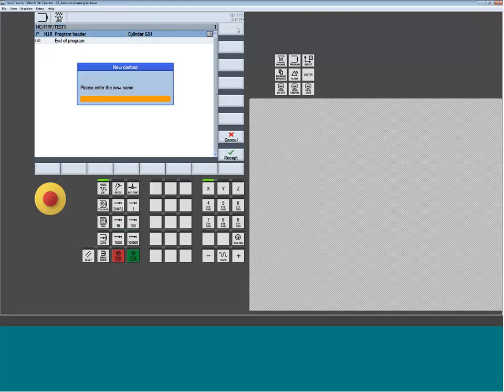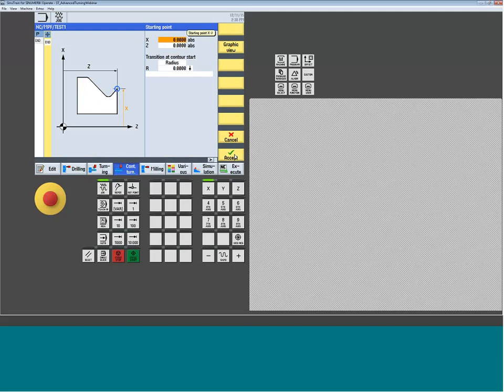Now we're going to want to go in and create a contour. The name of the contour, as in the past, doesn't really have any bearing more than it's just a reference for you. If you know you're doing multiple contours, I may start naming them with a number. You don't want to always have the same name, it can't be duplicated or they'll get linked. But then I start building them from here.